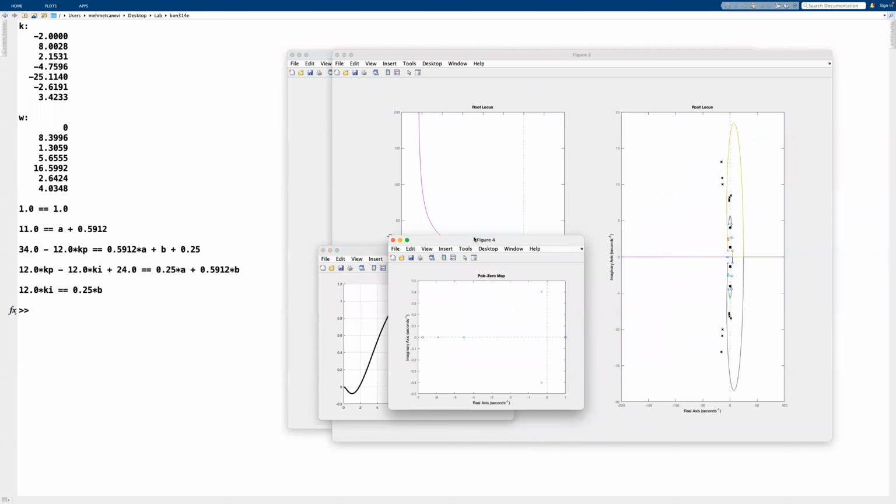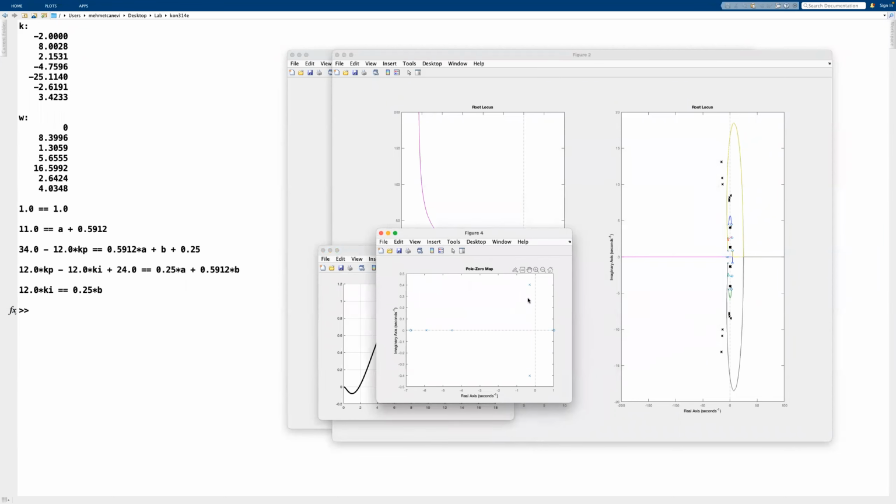Now, before I look at that, I wanted to check if the solution that I came up with is a dominant one. I am doubting that you can see it, but let me show you. This is here a 0 at minus 6.75. And then we have another pole at minus 5.9 and another pole at minus 4.52, whereas the pole pair is here. And we have a 0 at the right half plane. So it seems like this is quite a good solution.